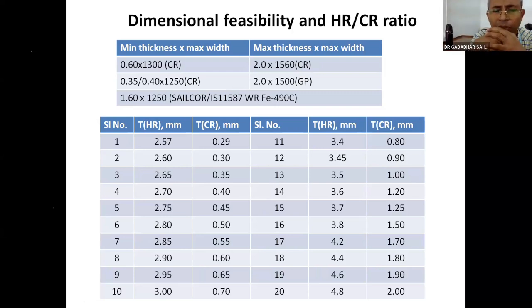See, we have 4.8 mm input material. If we give 2 mm, it will not give that much reduction. Suppose you are giving 30%, 40% reduction, we will reduce the reduction. We will give you the sheared material, no issue. It will comply with elongation percent and all, everything will come. It should comply. And the other reason I am telling is that the main constraint is not rolling 4.8 mm. The main constraint is that the load gets higher in thinner sections. And not only here, also in the HSM, the hot strip mill, there is a load constraint. So that way,